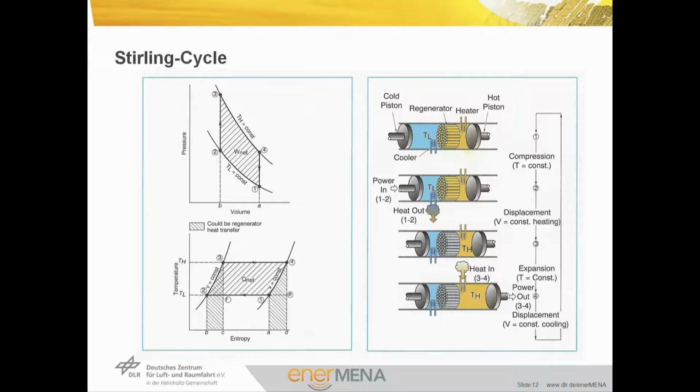To explain the functioning of the Stirling engine, you should first know its main components. The schematic engine is composed of 2 cylinders with their pistons, 2 heat exchangers, one for cooling and another one for heating, and the central component is a regenerator, which is a storage device for heat. The component not mentioned yet is the working gas that is enclosed in the engine.